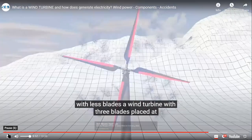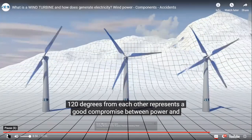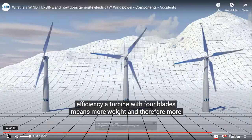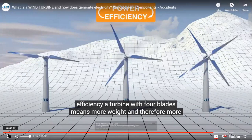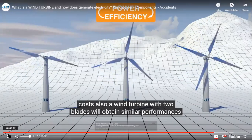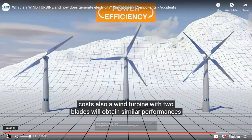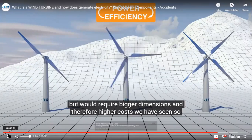A wind turbine with 3 blades placed at 120 degrees from each other represents a good compromise between power and efficiency. A turbine with 4 blades means more weight and therefore more costs. Also, a wind turbine with 2 blades will obtain similar performances but would require bigger dimensions and therefore higher costs.